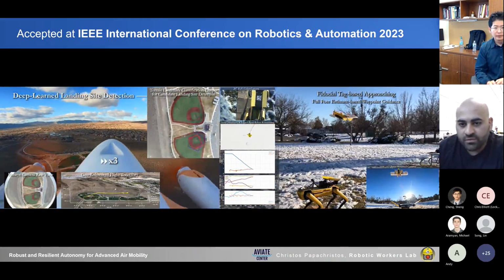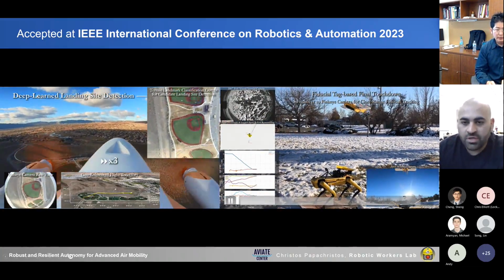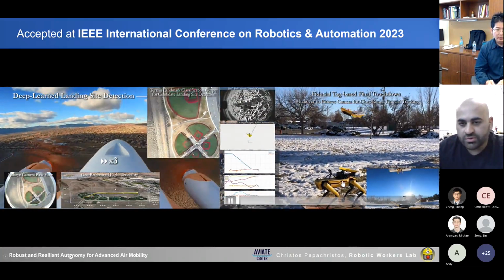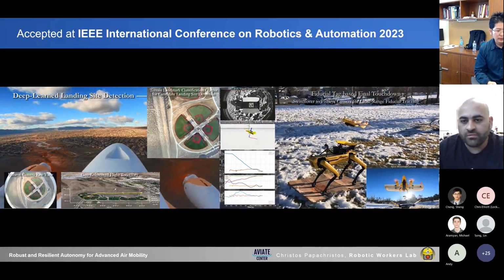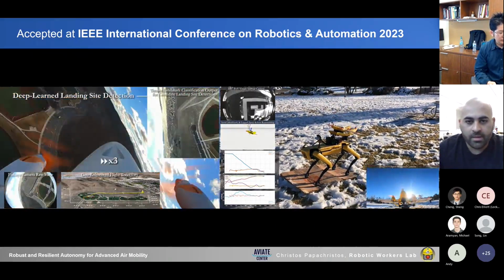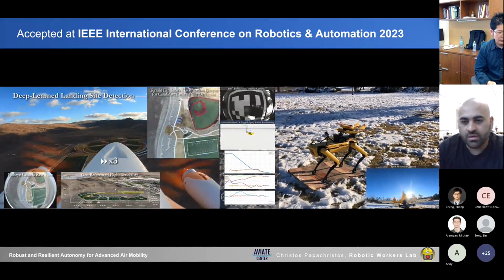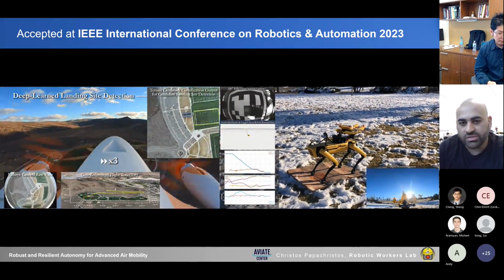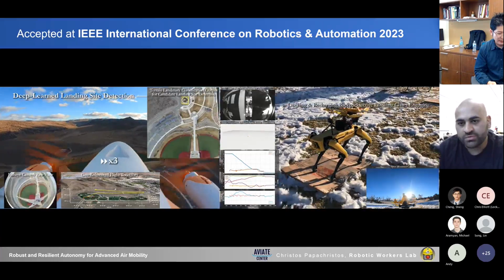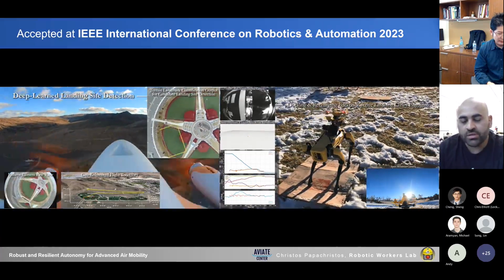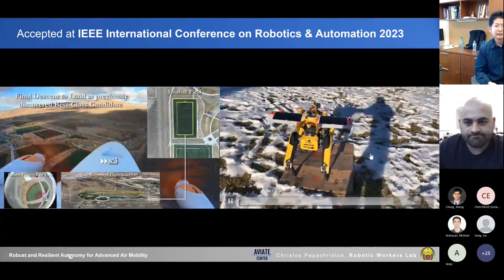And also we have some work where we can detect another system which can be used as a marsupial system to extend the operational period of Minihawk. By combining these modalities, we are able to recharge the system within 30 minutes as opposed to 3 or 4 hours, where we are just wasting a lot of time with the vehicle sitting idle.